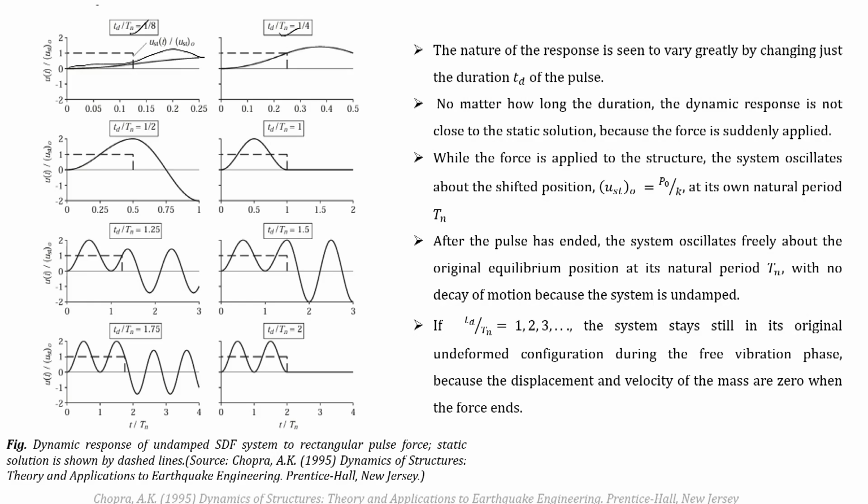What we observe is that the nature of the response is seen to vary greatly by changing just the duration of the pulse. If we change the duration of the pulse, the frequency of the system remains constant. For a given system, the frequency is always constant. So if we keep changing the duration of the pulse, we can see that the response of the system changes from non-oscillatory to an oscillatory response. No matter how long the duration, the dynamic response is not close to the static solution.